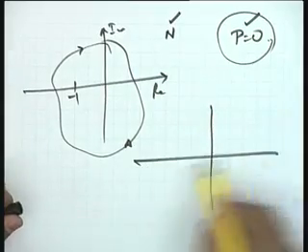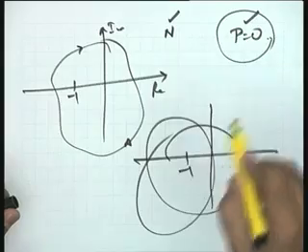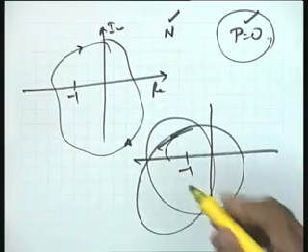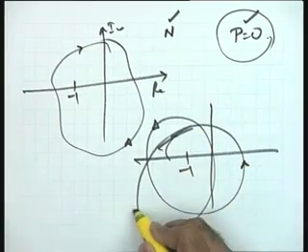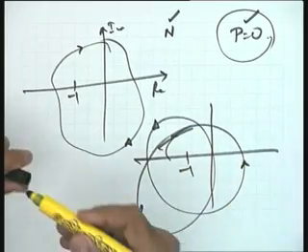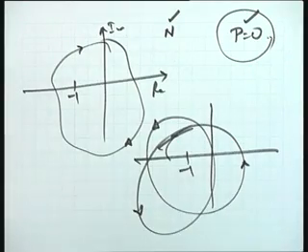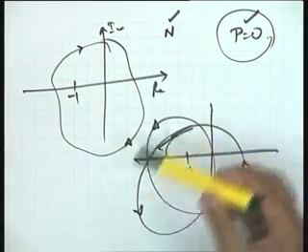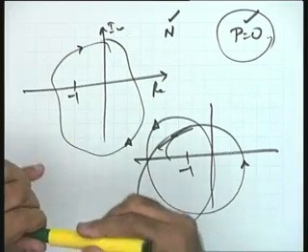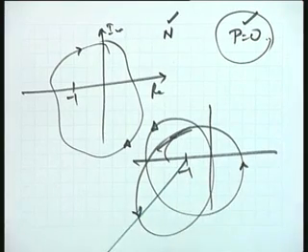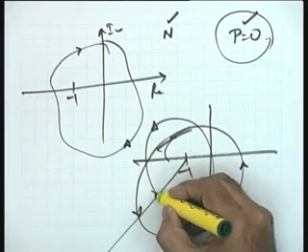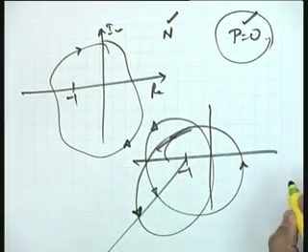Take another sketch. You see, this is your minus 1 point. Okay. I make this sketch. You see that I start from here, and the plot goes like this. Now in this particular case, please help me, what is the value of n? So you see that one thing is there, that you can count the number of encirclements. I give you a clue, you can proceed like this. Take your minus 1 point, just draw a line from this particular point in any direction you like, one line you draw from here, and just see how many times this line has been intercepted.